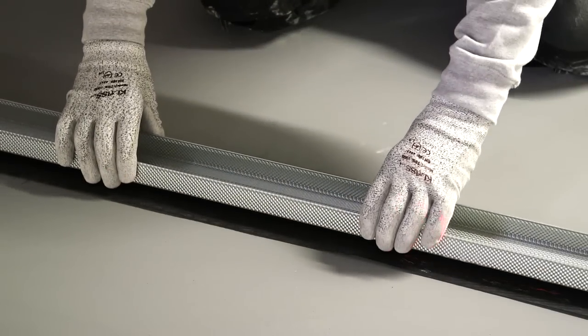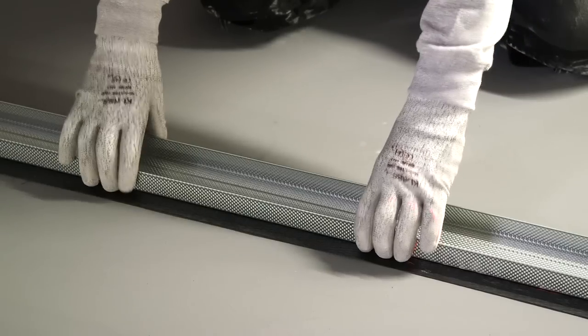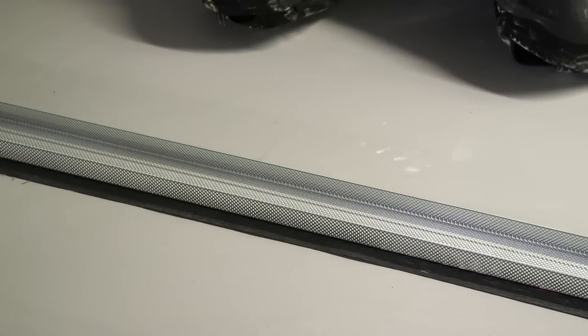On new concrete or screeded floors, consider installing a damp-proof membrane between the channel and floor to reduce the possibility of any corrosion occurring on the floor channels.